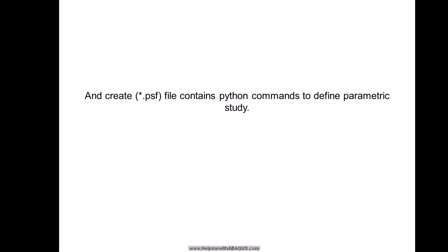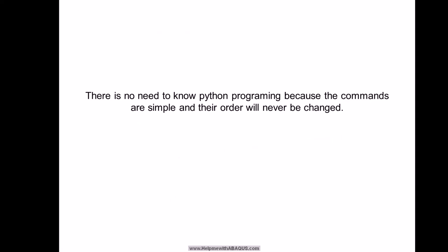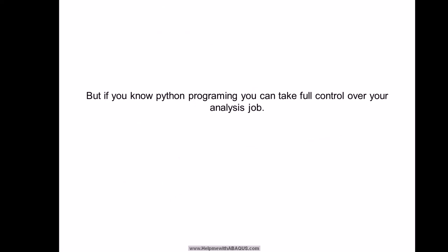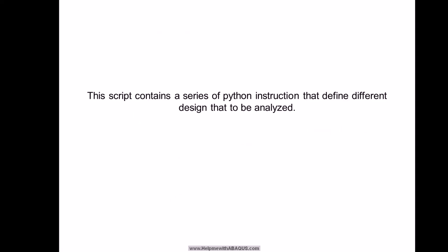Now create a PSF file that contains Python commands to define the parametric study. There is no need to know Python programming because the commands are simple and their order will never change. But if you know Python programming, you can take full control over your analysis job. This script contains a series of Python instructions that define the different designs to be analyzed.